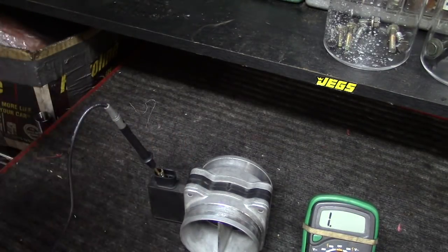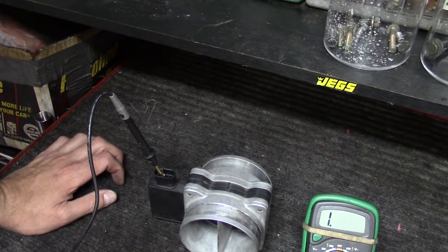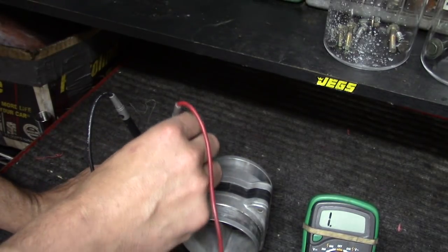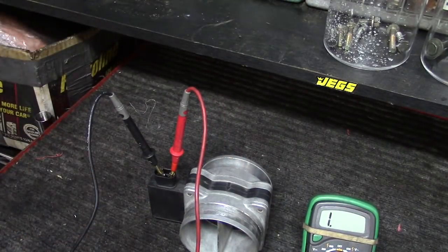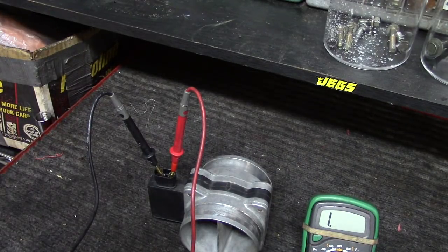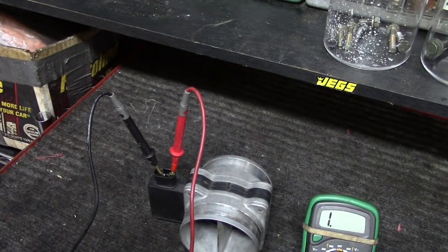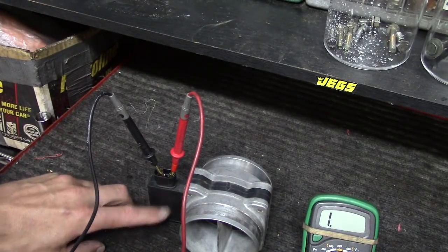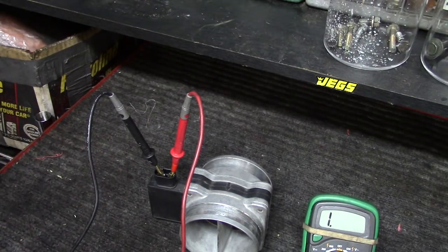Now the other thing we want to do: intuitively you would think we want continuity between the 5-volt reference and the ground, and we do not actually want that if we think about it, because that would be variable. So let's just test that, and we can see we do not have that. We would need power to this sensor, and of course it would vary based on the amount of flow. If we had continuity here, that would be indication of a bad MAF sensor. We would have some kind of short with the signal and the ground internal in the MAF circuitry, and that would be without question an indication of a bad MAF sensor problem.